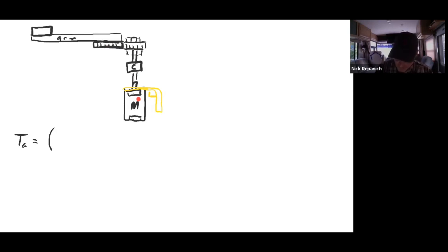But we know we're going to have 1, 2, 3, 4, 5, 6, 7 terms, 7 inertias that we've got to deal with. Some matter more than others. The hard part about this is you don't know which ones matter until you actually get the numbers out of the equation. You could guess at which ones matter, but you can guess wrong pretty easily here. So we have to write the whole formula correctly. And this is the I part of the I alpha, and somewhere way out here, we're going to have alpha. I don't think our 7 terms are going to fit in that, but let's see what happens.